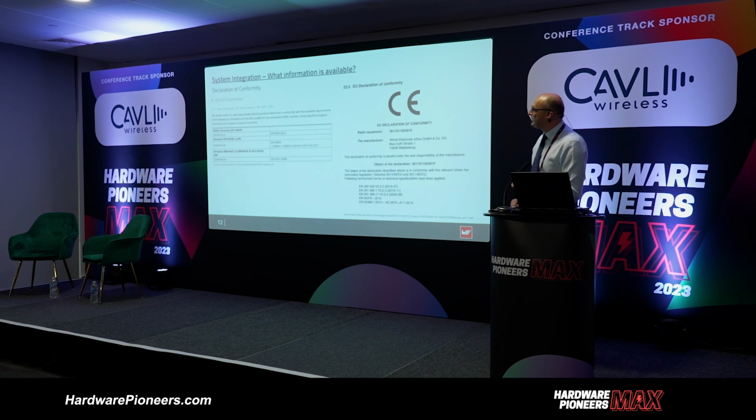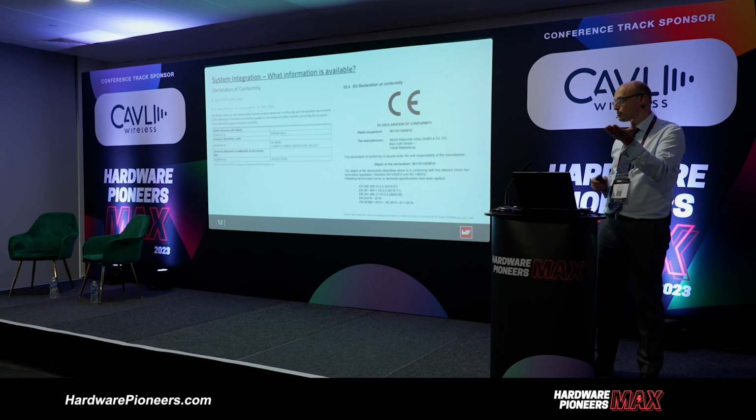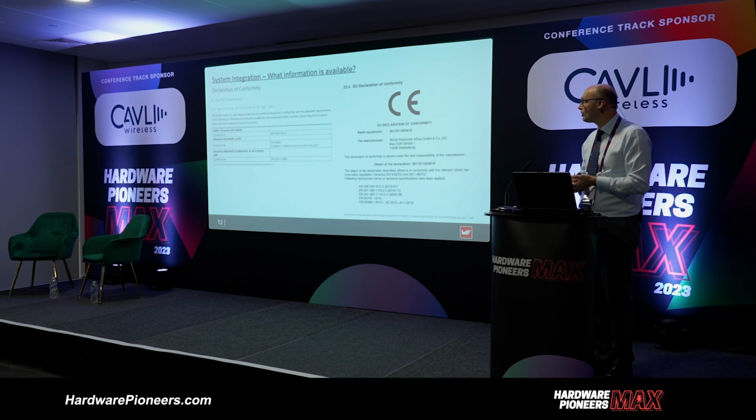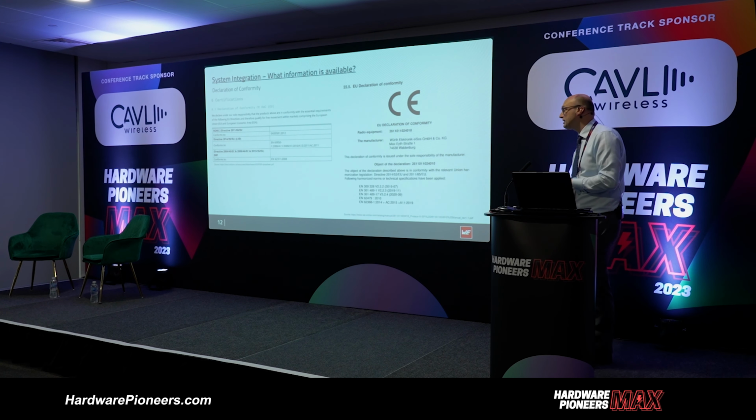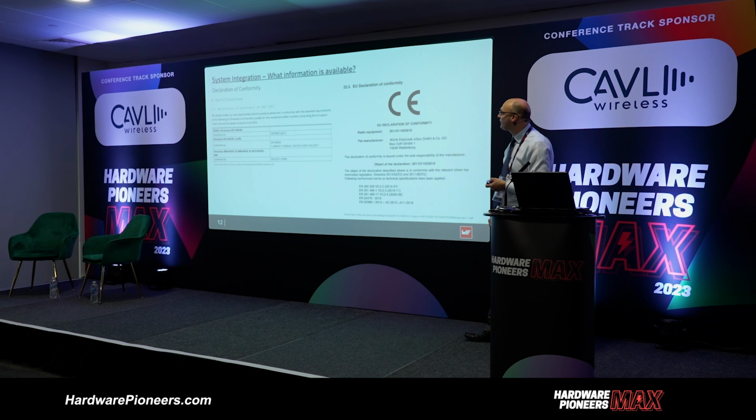Nowhere in there is actually anything with regard to EMC. So when I now take that particular product and I now place this RF module on top, does CE plus CE equal CE? In this case, no. So here's an example of our declaration of conformity for our particular Proteus 3 module.